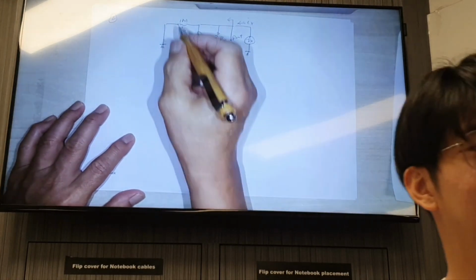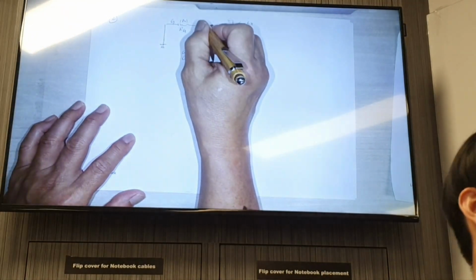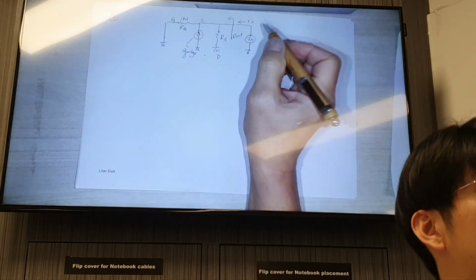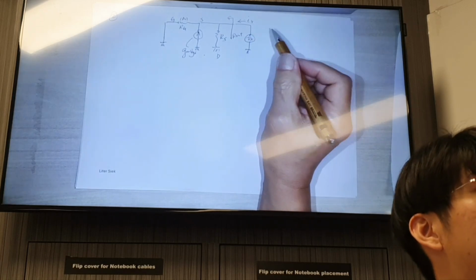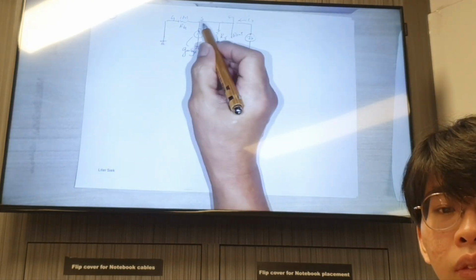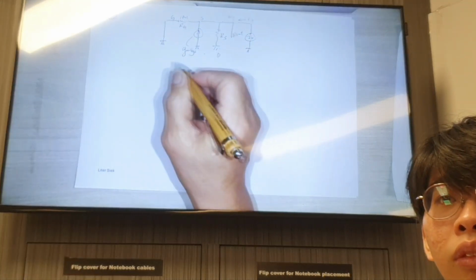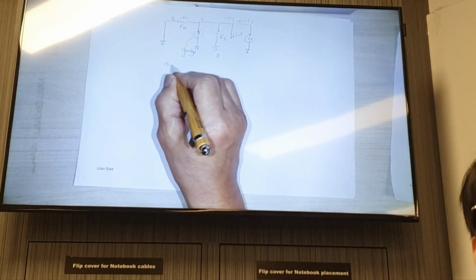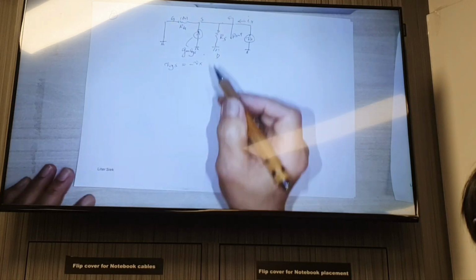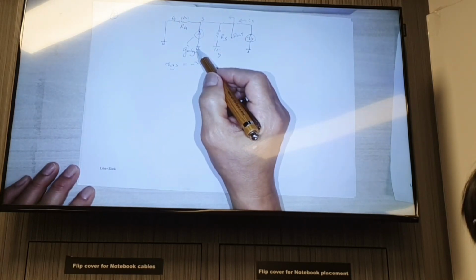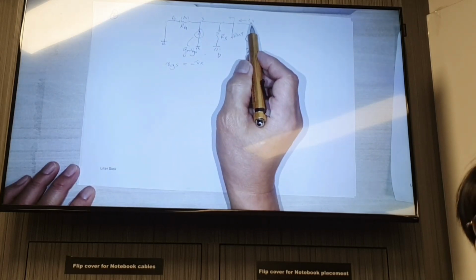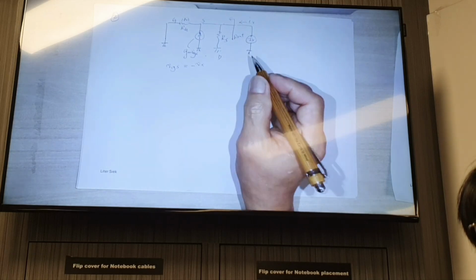So again, if you look at this, this is your gate voltage, this is your source, this is your gate. And the voltage at the fictitious voltage source that you put in here, Vx, is actually equal to Vs. Therefore we can write that small vgs is equal to minus Vx, because Vgs is Vg minus Vs. If Vg is 0, Vs will be the same as Vx, and therefore we have this.